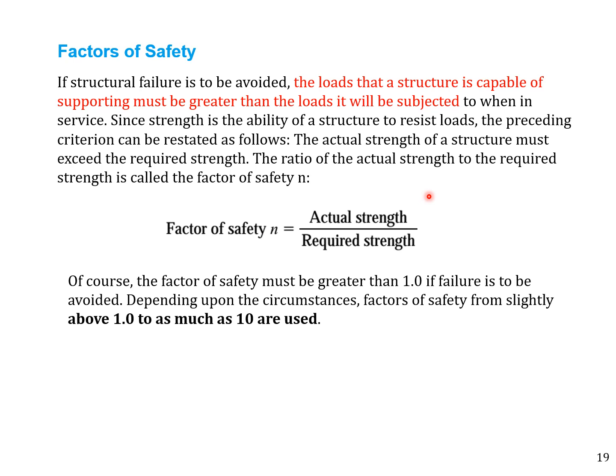For example, if we have a material with an actual strength of like 120 megapascal, and the required strength for a surface is 100, the factor of safety will be equal to 1.2. It means our required strength is 20% lesser than the actual strength. So the factor of safety must be greater than 1 while designing a mechanical structure.